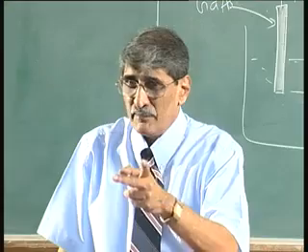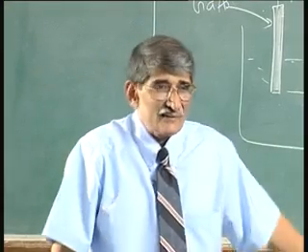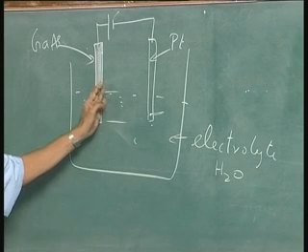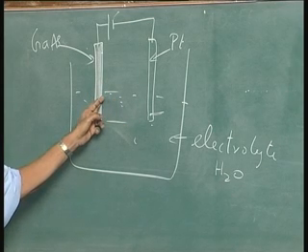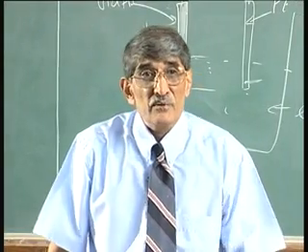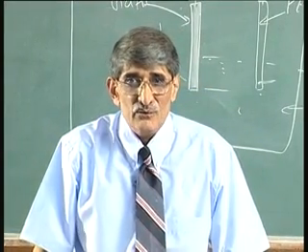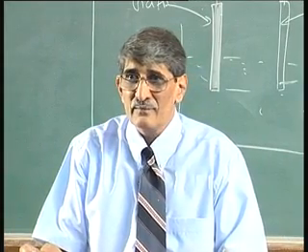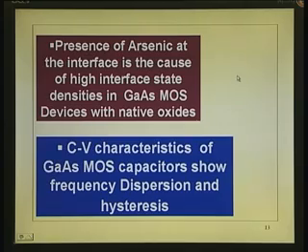Never forget, reverse the polarity, there will be etching. So, this is the one. When you do that, these OH ions actually get into the surface, react with gallium and arsenic to get gallium trioxide, arsenic trioxide. We saw stoichiometric oxides. No loss of arsenic trioxide because of room temperature. But the interface, you can guess, will contain arsenic, because gallium oxidizes better than arsenic. So, you have accumulated arsenic.